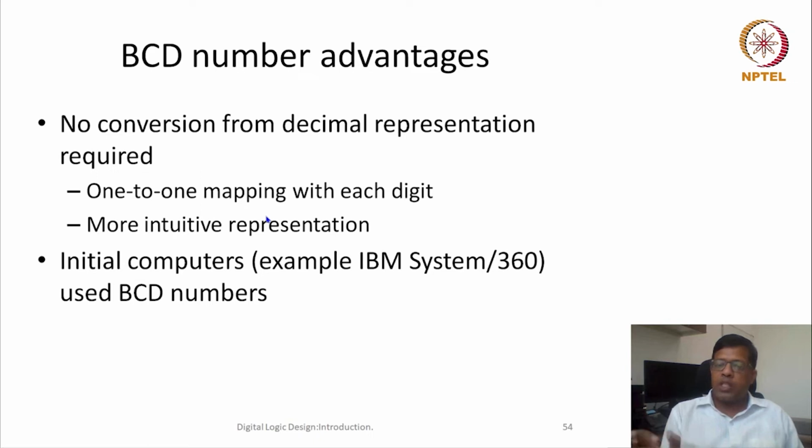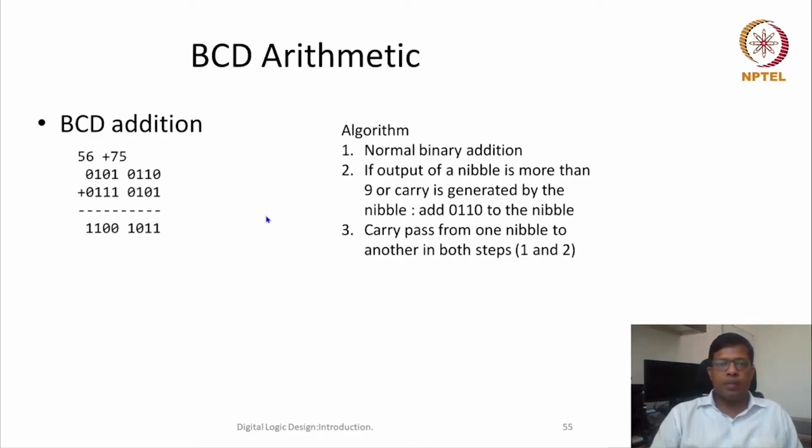Okay, now what is the disadvantage? For representing, it is good and sufficient, but when it comes to arithmetic, meaning addition, multiplication, subtraction, these BCD numbers become slightly complicated, because you have a gap of these 6 unused combinations. So let's say I want to do addition. I am taking an example, and with this example we'll be able to understand what kind of challenges we'll see.